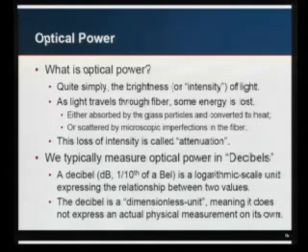We measure optical power in decibels. So a decibel is 1/10 of a bel, and it's a logarithmic scale unit for expressing a relationship between two values. It's what's called a dimensionless unit. It doesn't represent a physical quantity. It's purely a math concept. It represents the difference between two other quantities.